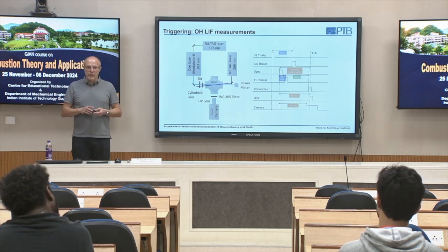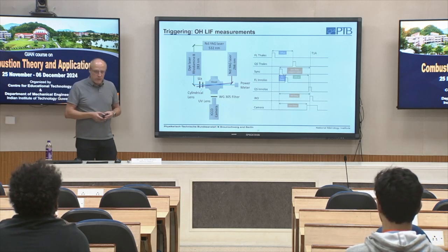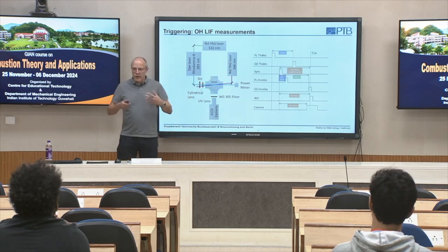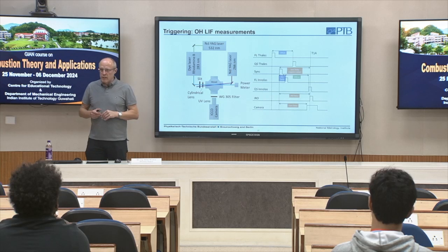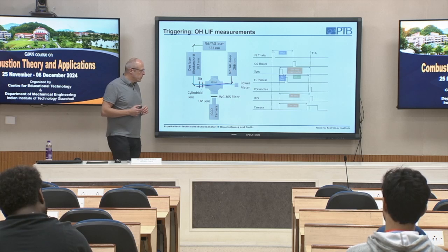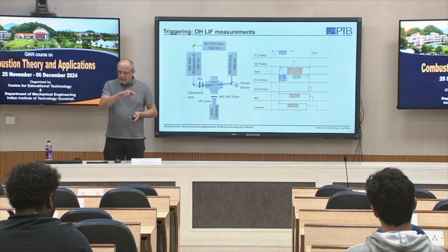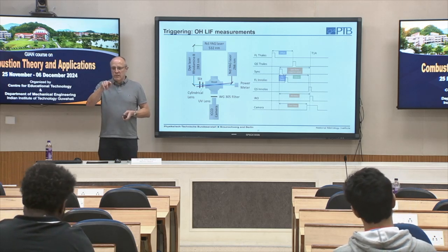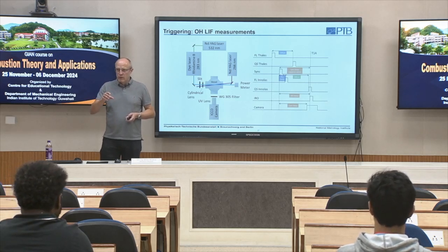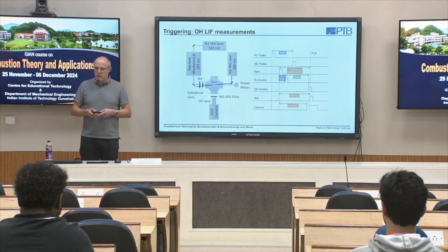Nevertheless, when we trigger on this event, we have a problem. We have a lot of delay between triggering and firing the laser, getting an image. So we have to trigger on an internal event. The breakthrough appears at a given voltage, but it appears due to the fact that we have some startup electron in the system formed by UV radiation from the sun or whatever. And this, of course, is a quite arbitrary process.